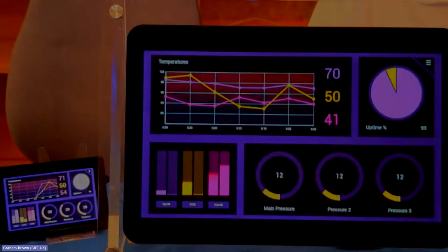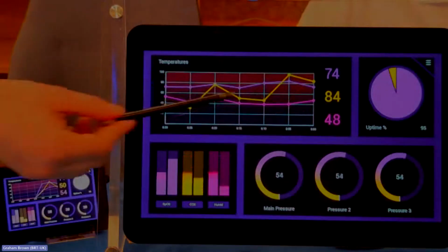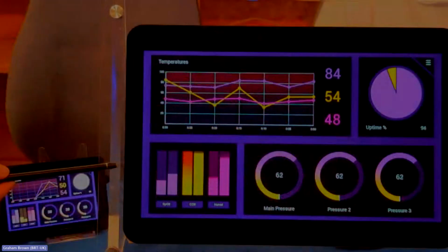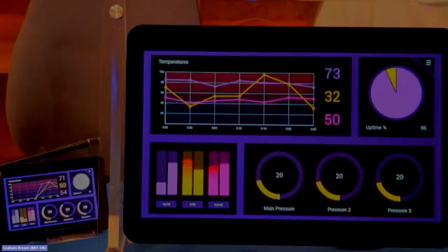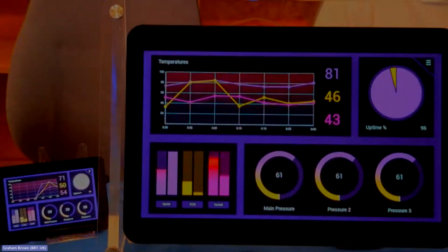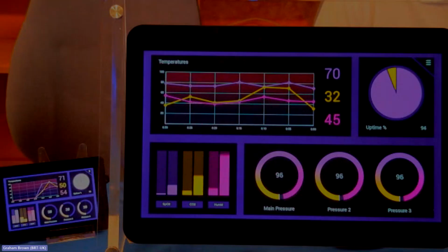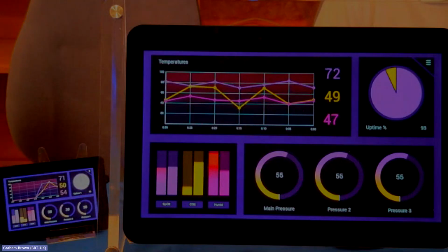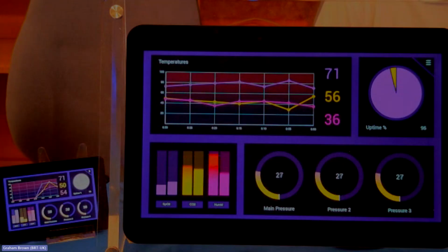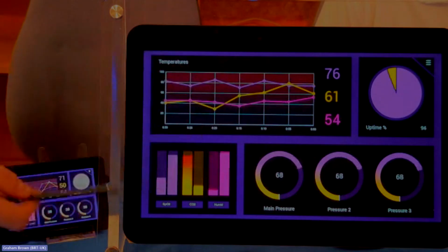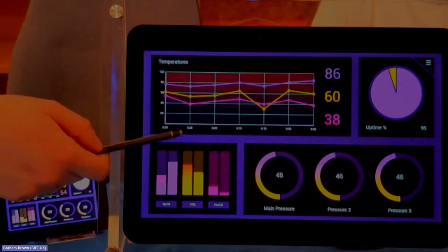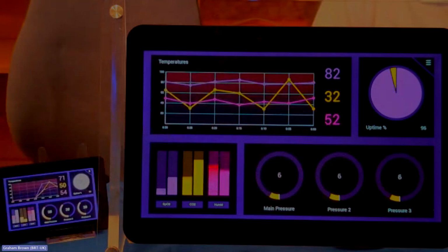So we've just switched camera here. And as you can see, here is the data visualizer example. The first one here is running on our BT820 based 5th generation Eve on a 15.6-inch screen. The second one down here in the corner is running on our FT813 based Eve solution on a 5-inch screen. So the idea behind this example is that it is supported on all Eve generations, and it shows that you can scale this example as required through resolutions. So this is a 800 by 400 screen, and this is a 1920 by 1080 screen.